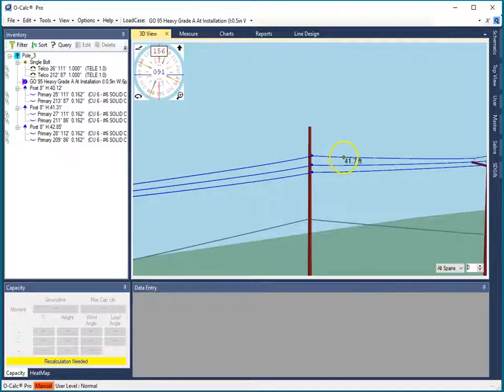In addition, the span on the proximal poles on either side also got adjusted, and this span's geometry also got adjusted so that the span's angle and length are all correct to go to the far support. It just makes my life a lot easier when I'm dealing with series of poles that are in fact connected. In later videos, we'll see how this helps us out when we're doing clearance analysis as well, because there's actual connectivity. Tagging a single span or a single set of spans means that that span now knows its type and its clearance rules all the way down the line, and I can get a very quick set of clearance rules out of the system.